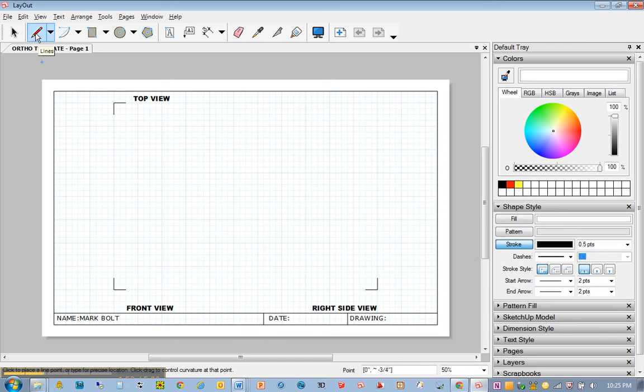So with the pencil, or excuse me, line tool selected, which is L on your keyboard, I'm going to click here, and this grid is set to 1/4 inch spaces, and these blocks are a distance of 1 inch. So you can see there's 4 divisions. So this is an inch, 2, 3, 4, 5, that's 6 inches. And I could click, and that's one way to make a line. Another way to do it, which I recommend, is clicking once, move in the direction you want to draw the line, and type in the number. So I will type in 6 for 6 inches.